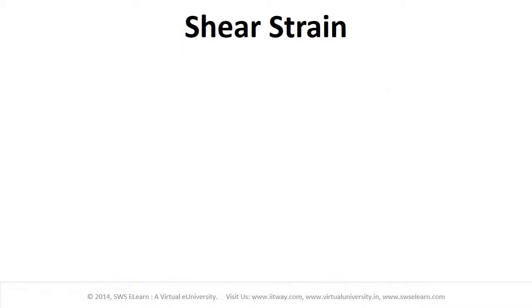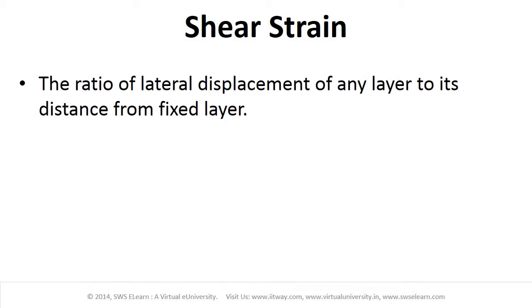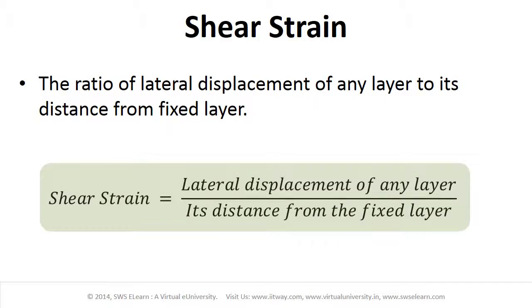The shear strain is defined as the ratio of lateral displacement of any layer to its distance from the fixed layer. In the equation form, it is written as shear strain equals lateral displacement of any layer upon its distance from the fixed layer.